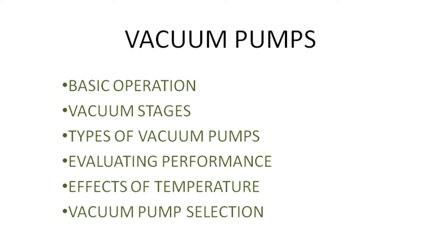Internal pump temperature: operation at high vacuum increases pump temperature. That means when we need vacuum pumps for creating higher vacuums, the internal pump temperature will affect its operation. Heavy duty pumps with cooling can operate continuously, but light duty pumps can operate at maximum vacuums for only short periods, and they must be allowed to cool between cycles.